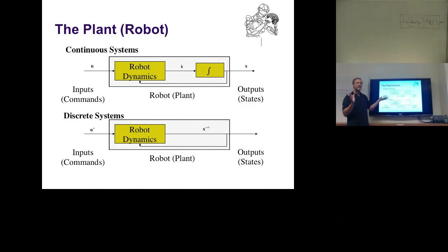In robotics, we usually run control systems between 100 Hertz and 5 kilohertz. These are significant time steps, and discrete systems actually matter. You will see in one of the next lectures how the change from a continuous system to a discrete system makes a big difference in how stable a system can be.